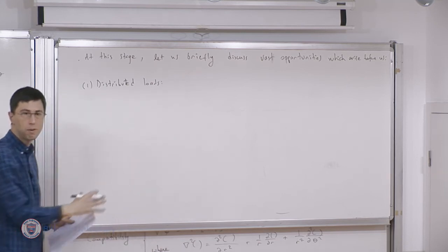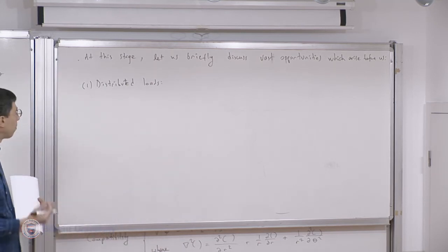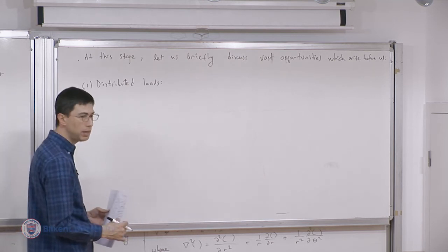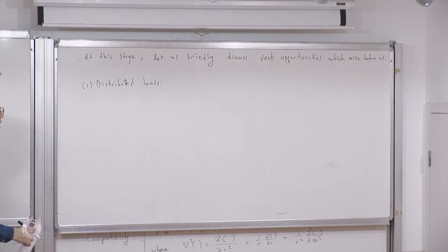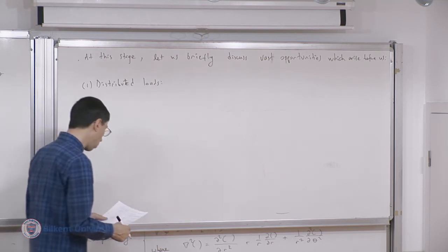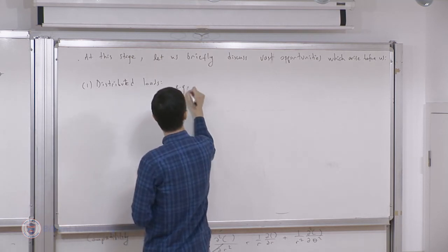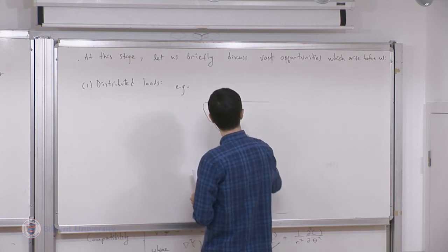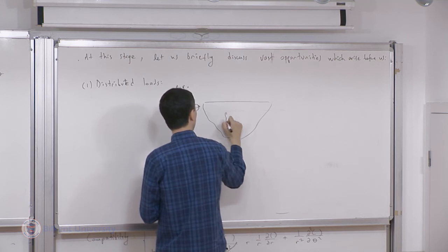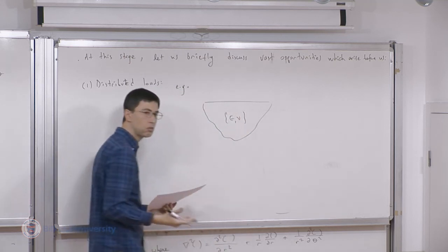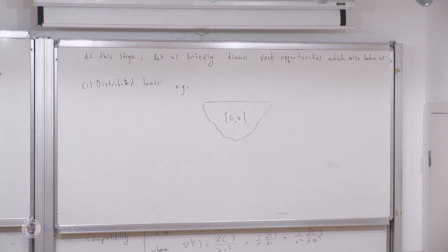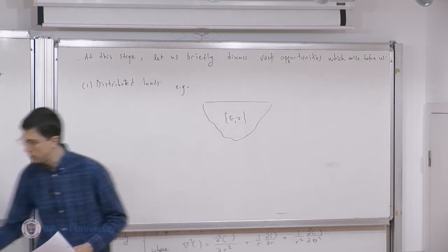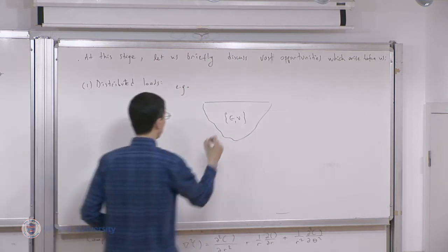I'm not going to solve anything more. I'm not going to be very rigorous or precise with the discussion that is about to follow. I just want to give you an idea of how the solution that we have just completed is a step towards dealing with more complicated problems. So the distributed load would be a setting that is quite similar to the setting that we have looked at. We have a domain. The domain is deformable. It has a Poisson ratio and a Young's modulus that characterizes the domain. But instead of a pointwise force, I will assume that we have a distributed force.